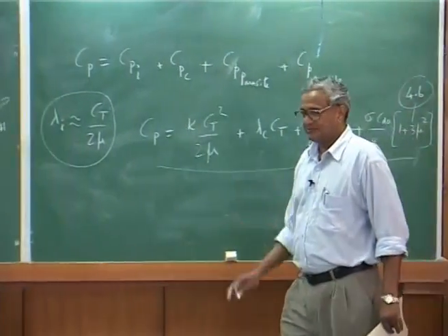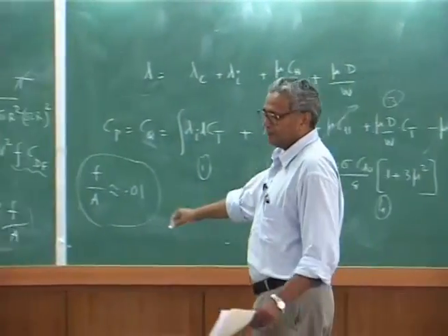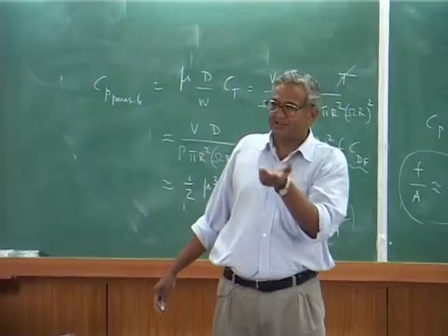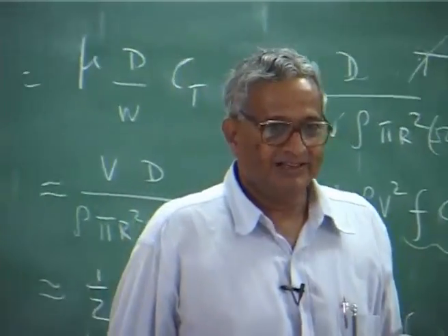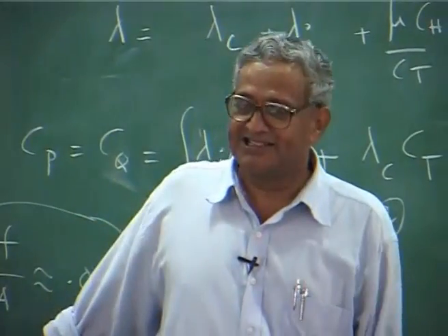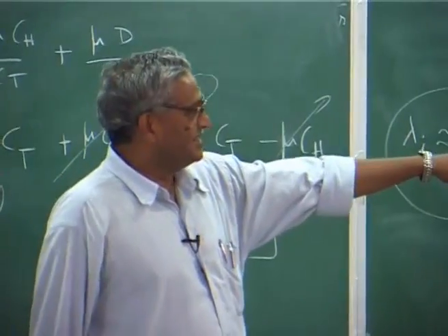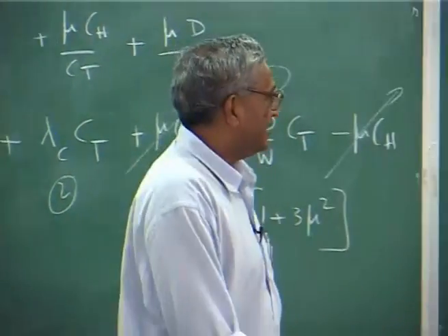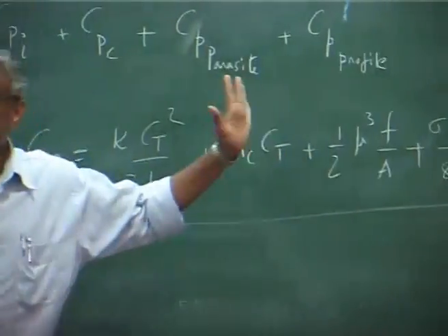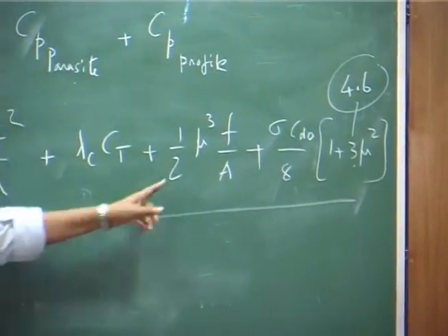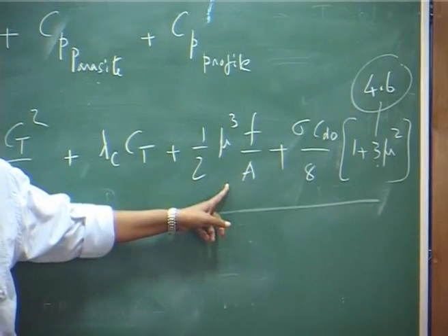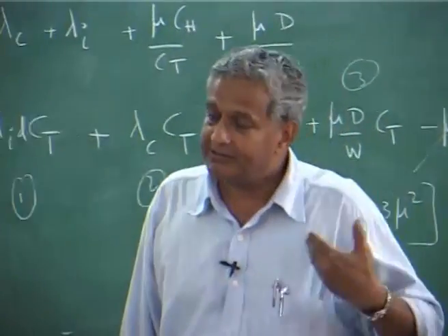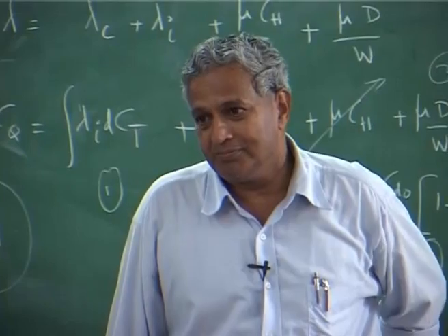Because again you make those assumptions, because this is a skewed flow, it is like a flow over a swept wing, and then try to get the equivalent value. After that you do the same integration, take an average, and instead of 3 it becomes 4.6, that is again some approximation. Now you have your complete power. Now you see, that is why the fuselage drag is actually cubic to the forward speed. So as you increase the speed, that power will tremendously go up.